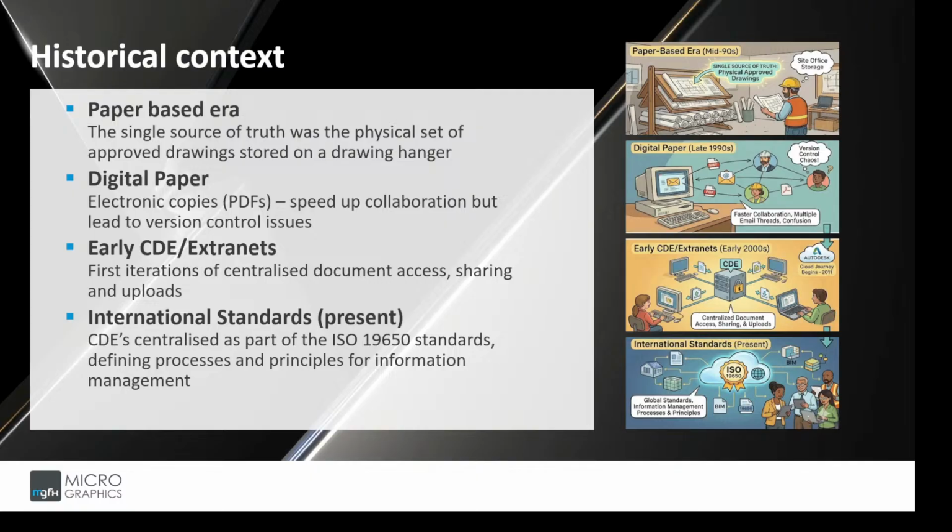When we're looking at the present, we have the international standards. Common data environments became an integral part of global standards, primarily the ISO 19650 series, which some of you might be quite familiar with. If you're not, we will also briefly unpack it later on in the webinar. ISO 19650 defines the processes and principles for information management during the building lifecycle, which is quite critical, and aims to address all the challenges faced by building stakeholders. Okay.